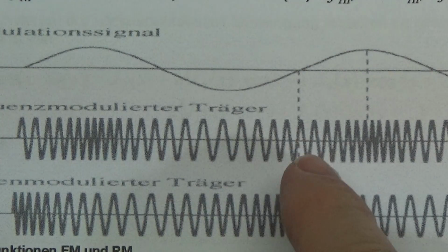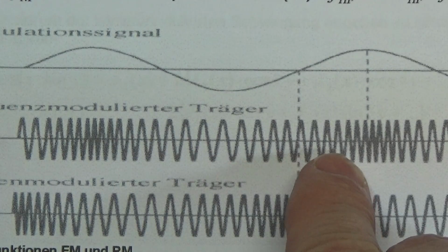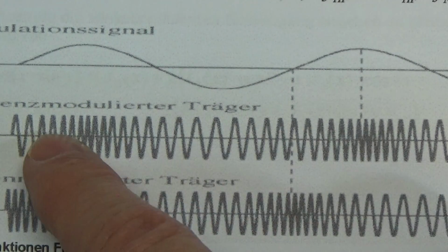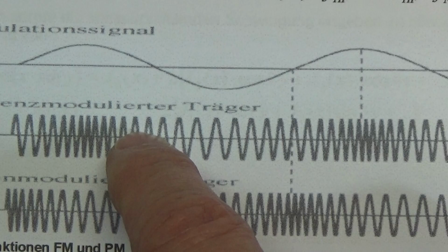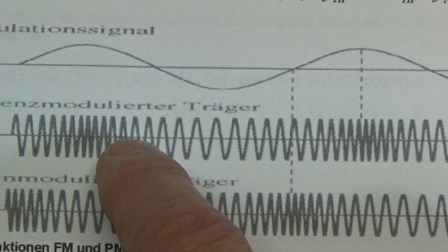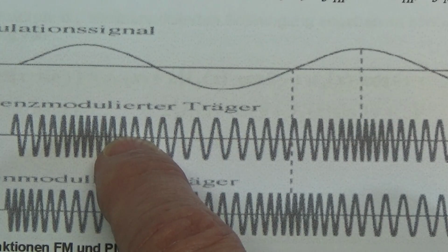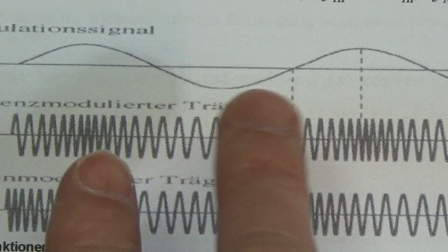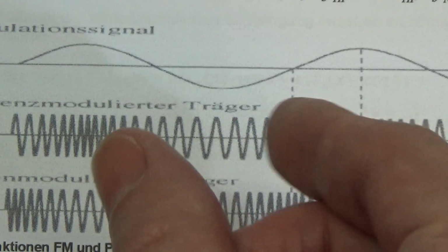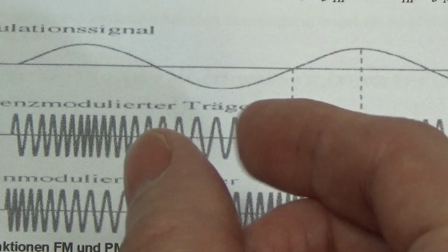And again, if we see what is happening here, if this is our carrier frequency, we see that we change our carrier frequency with our FM modulation, and we do two things. First of all, our audio, and second, our deviation. And basically you see that we are spreading out here our signal.